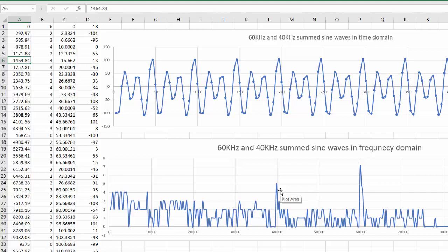All right, well, that was easy. We sampled at 300,000 samples per second. We captured 1,024 readings. We're not showing all of them in the time domain. And then we did our FFT to look in the frequency domain using the Adafruit library. So with that said, let's look at the code.